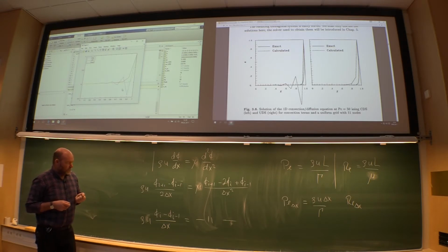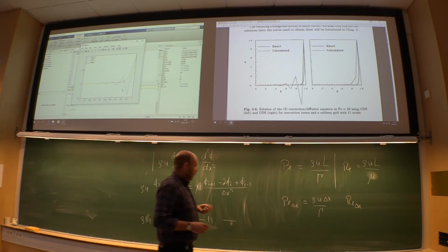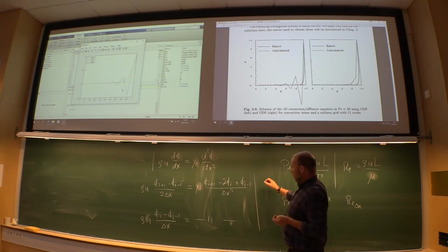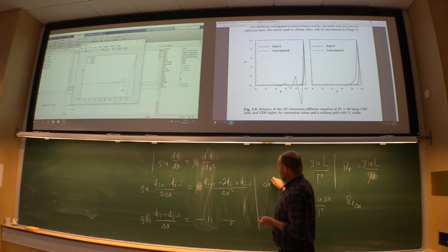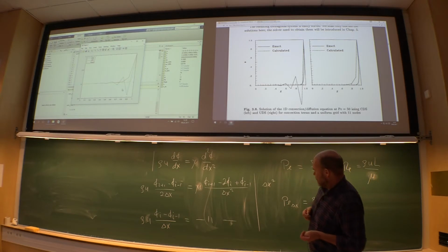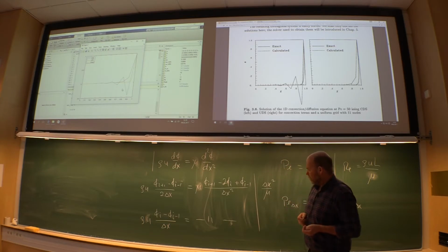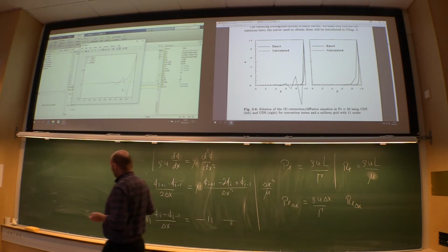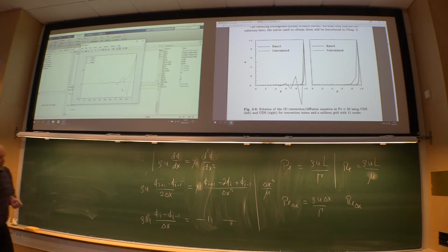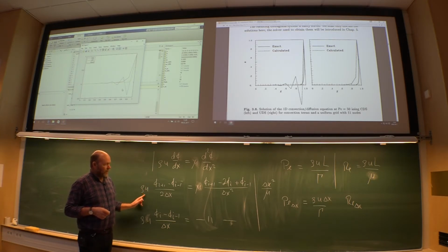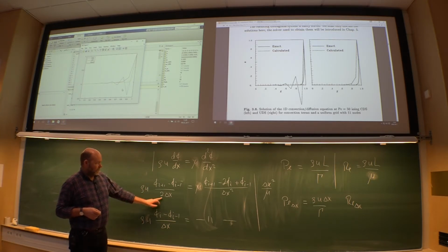Well, if you rewrite them, let's see now, we multiply these equations with delta x square divided by the viscosity. Both of them. Then what happens? Well, here to the left, what do you get? You will get the cell Reynolds number, rho u times delta x divided by the viscosity. And here I have 1/2.